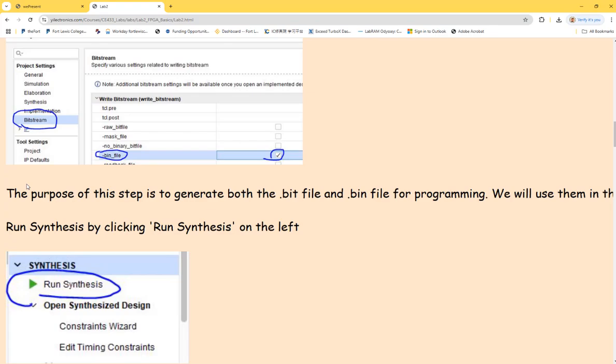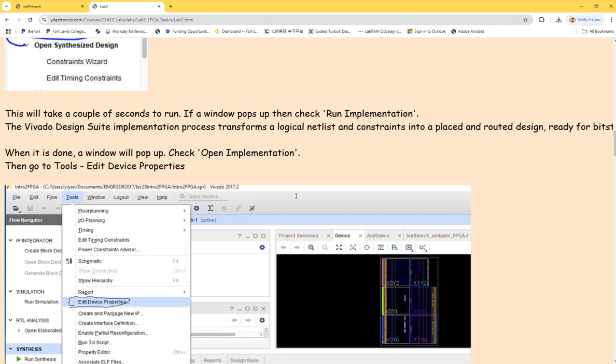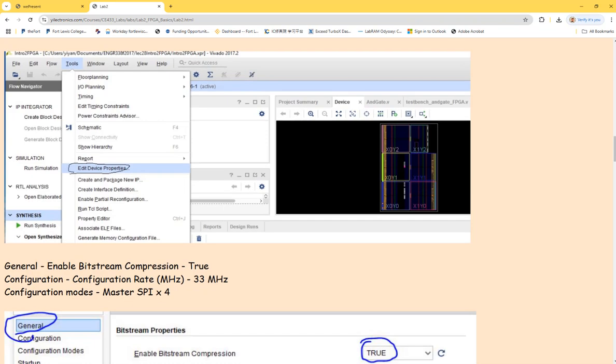That's the bit file. That's usually what we use. Okay, the .bit file, right? That's a regular file being programmed to the board through the JTAG port, which is one of the ports on the board. So just follow the regular process. We're programming the board using the bit file.